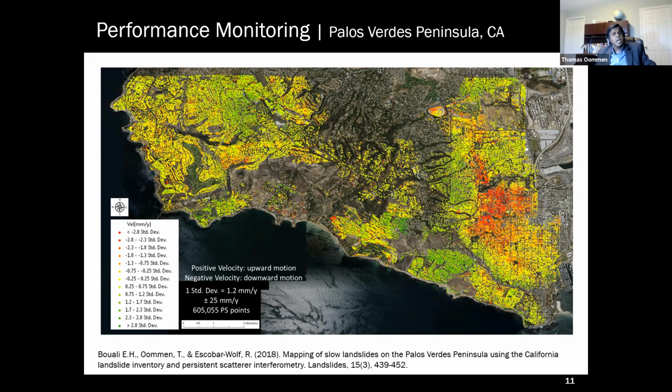Now, here you can see there are some areas where there is a lot of settlement happening. If you know the geology and the things happening in this area, there are actually some oil wells here, and these settlements are caused by the ground settling from the oil pumping in this area.